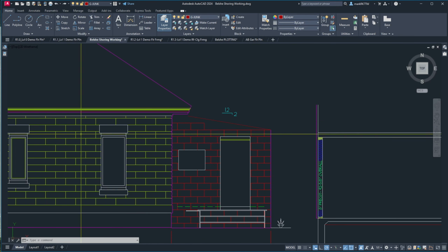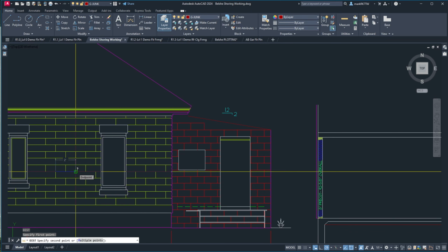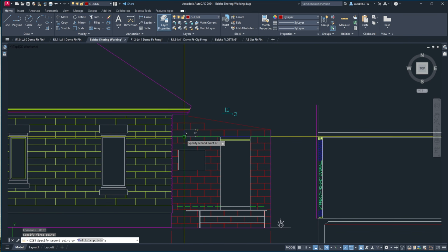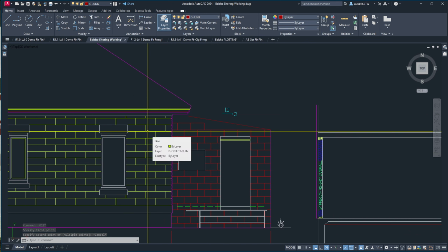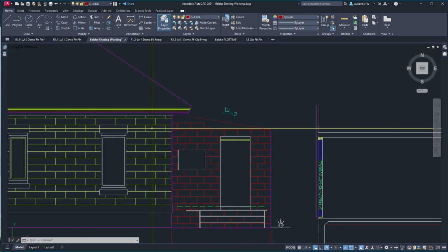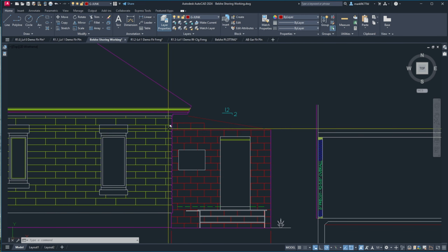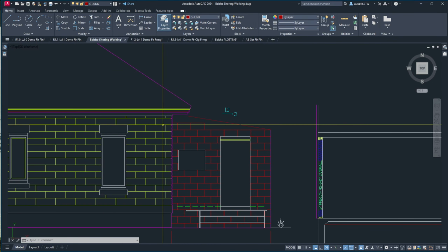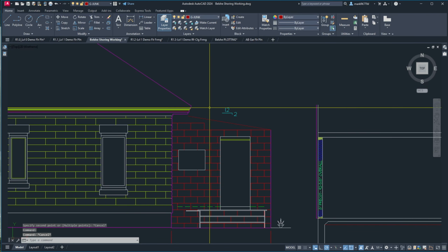Having it its own special case, because these are Sears and Roebuck blocks, and so some of these things are like 24 inches wide, and so here these are standard 8/16s, and so now that this is done, I want them to be on this layer because in AutoCAD it's a printing issue. My line weight prints, and my junk layers or my general layers don't print. But this thin, it's called D-object thin. It's a very thin line when I print it.